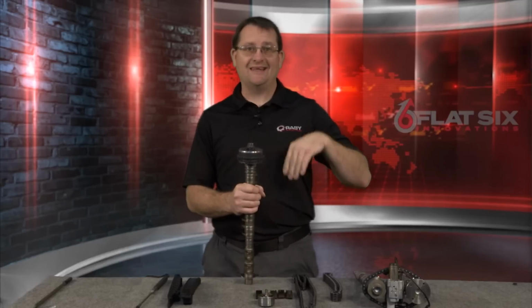Sometimes people think that will make it advanced, but a lot of times it still is going to retard because you're going to have all the valve train try to stay in one spot, and the crankshaft is going to zing a little bit higher, and you're going to have things stretch and move more toward the retarded side. So in these engines that have the vane cell adjuster issue, they will slip, and a lot of times they'll go like 90 degrees out of camshaft deviation, which is huge. That can even be to the point where you end up bending valves because you have valves hitting pistons and things out of time.